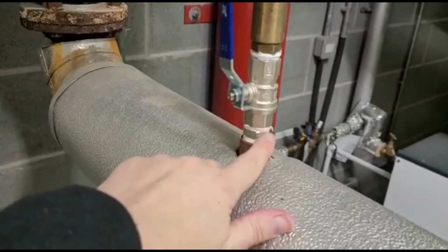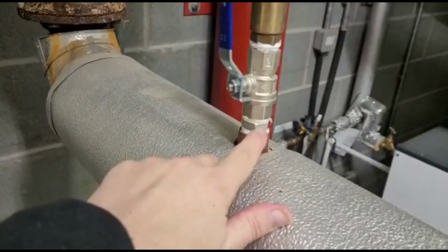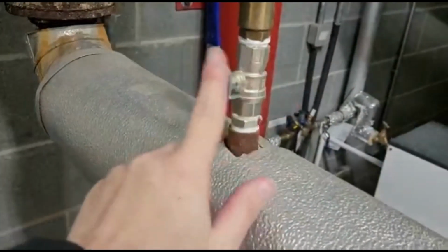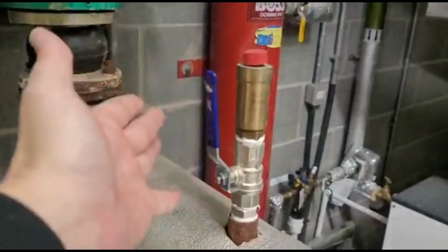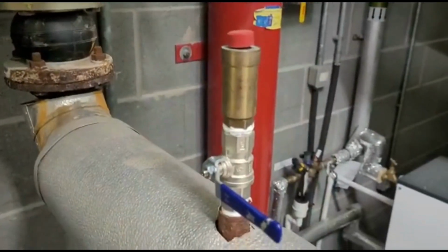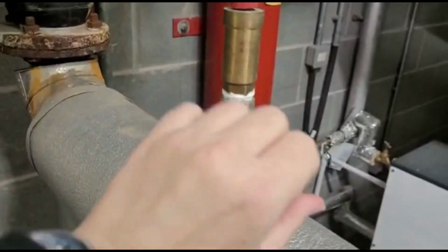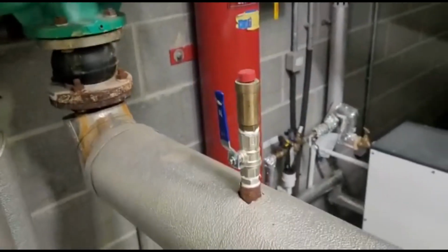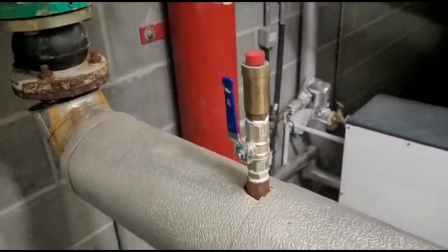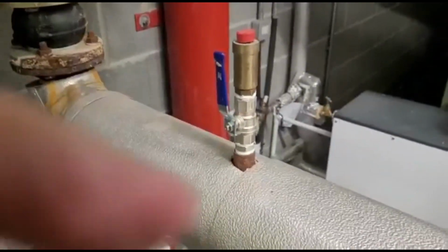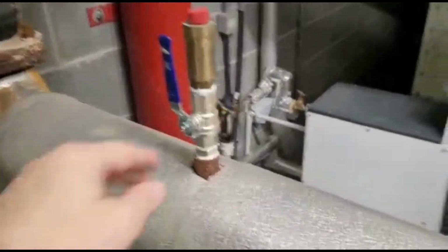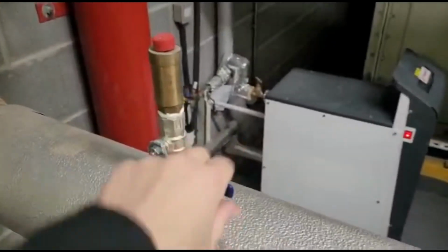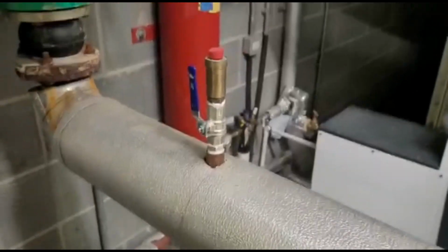Always use a stainless fitting, because mild steel rots, and if you do take it out at any given time, it's got every chance of snapping in there, and you don't want that. I do this because all you have to do is go like that, spin it off, throw it away, put a new one back on, switch it on. How easy is that? Dead easy. It's the future. Use 1/4 turn ones though, don't use tap isolation valves like under the sink where you've got to use a screwdriver, because they have a tendency of weeping after you've been faffing about with a screwdriver. Always use a quarter turn. Right, dead easy, simple as.